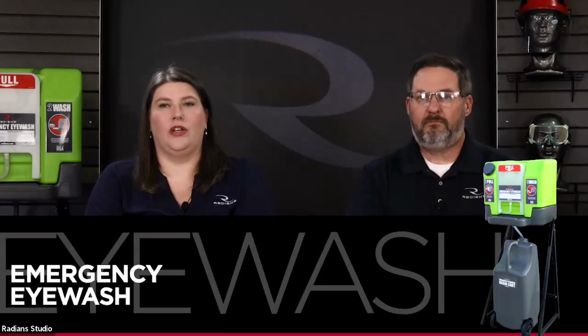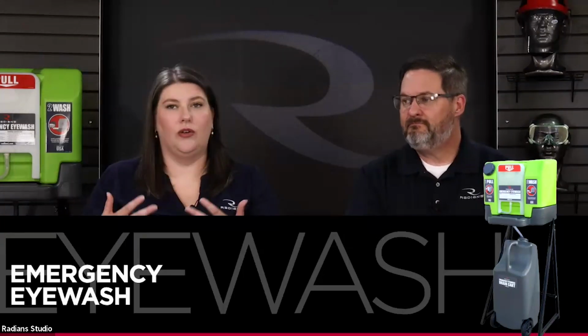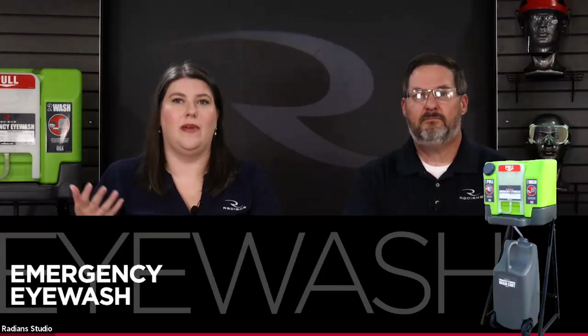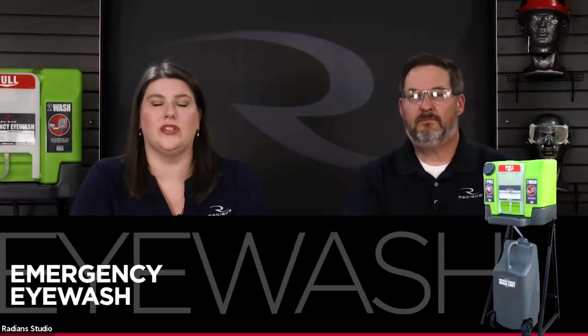You don't want someone of average height to have to squat because the station is too low in order to reach the water stream to flush their eyes. And on the flip side of that, you don't want the station mounted so high that someone has to stand on their tippy toes or can't reach the water. It's got to be within a certain range for the average person.